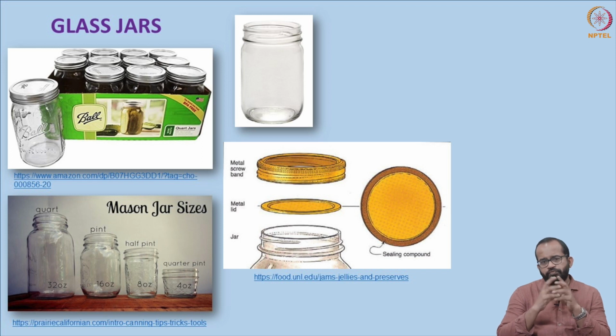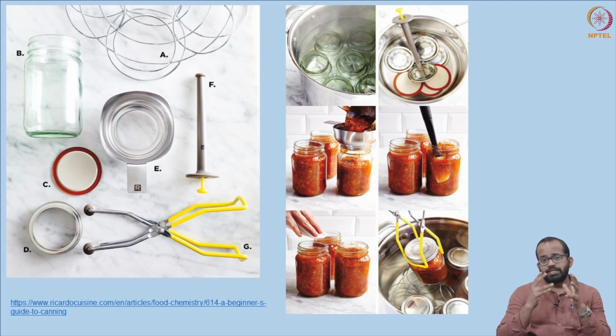It is also termed fused quartz or fused silica, because we use a thermal fusing technology to make it into an amorphous solid. So silicon dioxide is basically the purest form of glass. The key property we look for in glass containers is high resistance to thermal shock, because in thermal processing the glass should withstand the process.